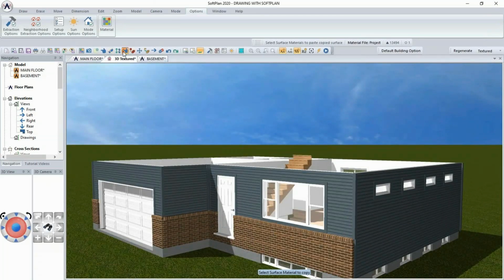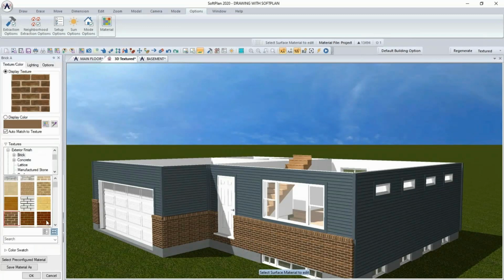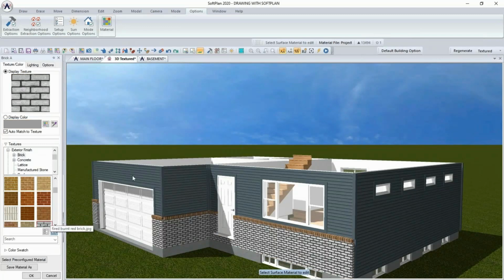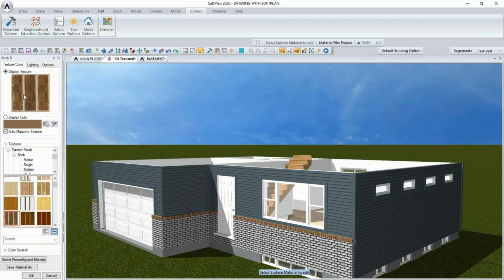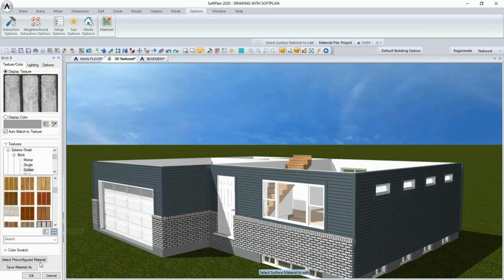One more trick here, I'll go to another surface edit, click on the brick. I'll choose this grayish tone brick. Notice it's only going to change the brick itself. The row lock or soldier course has not updated. I'll do a different edit on that because it does belong to a soldier course texture. And I'll just pick the equivalent gray brick that's there.